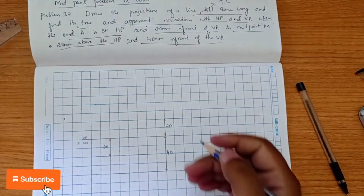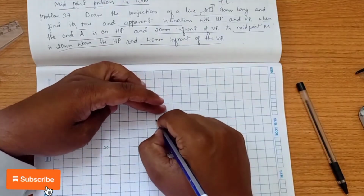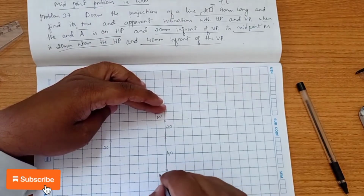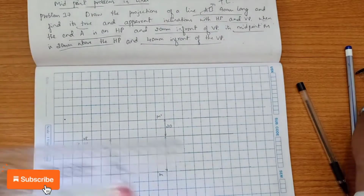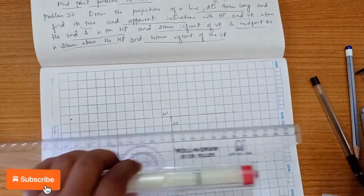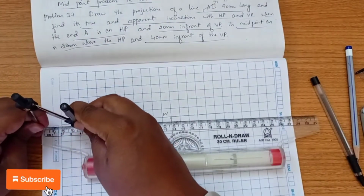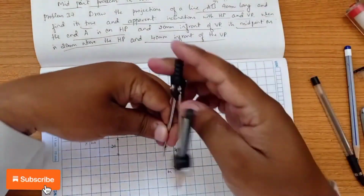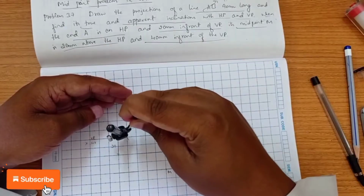Okay, so I'm going to mark a middle point here. This is M dash, and here we have M. Okay, so the middle point is drawn. Now we have the true length of the line, which is 90, so half means it is 45. So we have to consider 45 length. Here from this point on the XY I'm cutting the first arc.